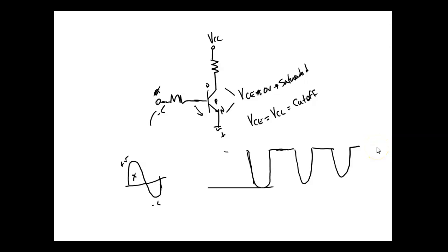By the way, we've used this circuit to convert 60 cycle into a digital pulse. So we made a digital clock. And Alabama Power 60 hertz is nice, right? You understand that? So we ran it through one of these guys right here, did a little work on it, saturated it. So it saturated real fast. So we ended up with just like this. When it's saturated, we never got to peak. We fed that into some dividers, divided it by 60, came up with 1 cycle per second, ran that into some counters, and set up and designed and actually built the digital clock. It still might be around here.